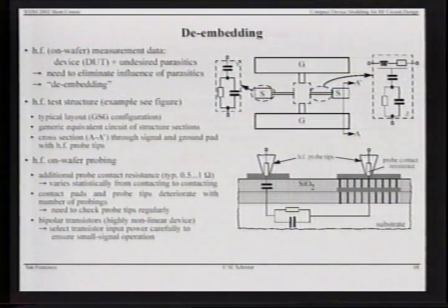From what we have learned before, we can represent the signal pad here by a lumped equivalent circuit, for instance, like this, and we can represent the lines at high frequencies by a lumped equivalent circuit like this, for instance, which we will need in order to de-embed the actual characteristics of this device from all these parasitics that are sitting around it.